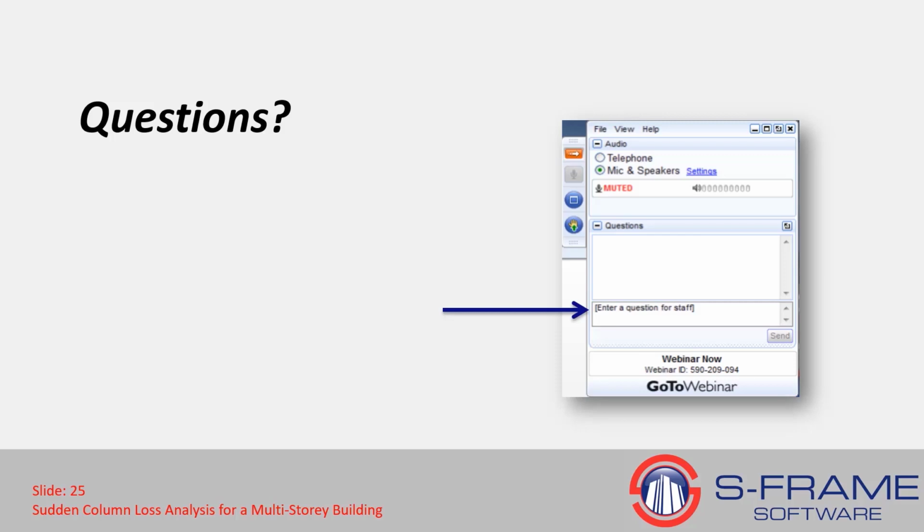With the variable time step integration, you use an initial time step size, and you define the range of time steps, and by using the critical jerk, the software will be able to detect where we might want to focus our attention in the analysis. So it basically is looking for any points of interest in the curve or any spikes, and will use higher frequencies of time steps in those locations. In that way, it won't have to spend too much time in the less interesting parts of the curve.